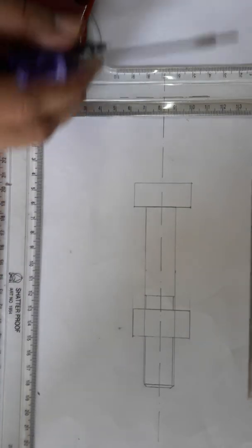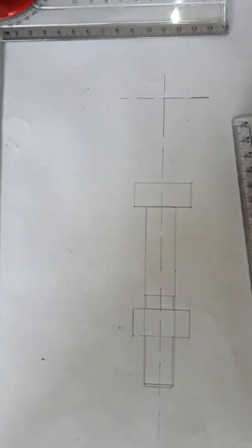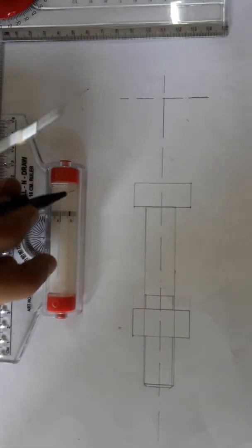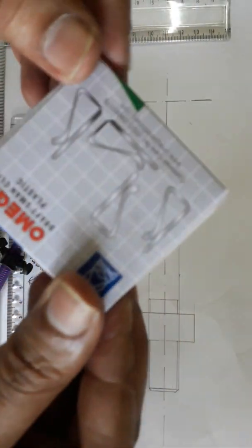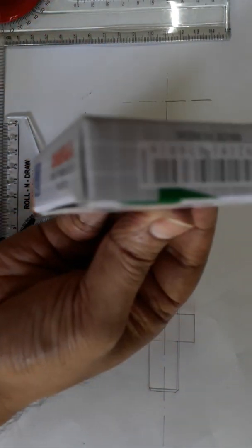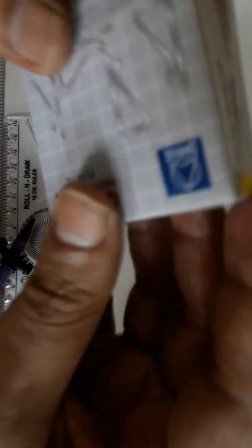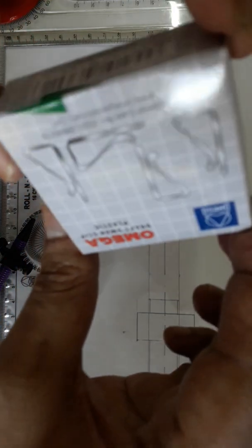Now, you get two faces in the view across corner, but you get only one face when you view across the flat. The bolt has a square head. If you view from the corner, from the front view you can see two faces, this face and this face. But since it is view across flat, in the front view you can see only one face.